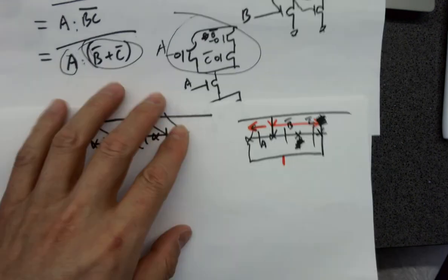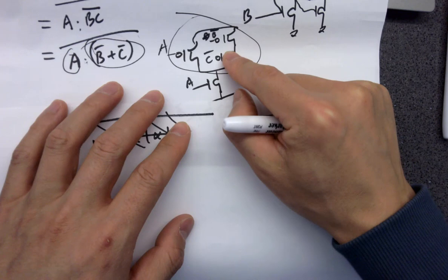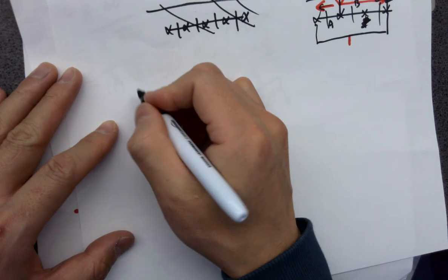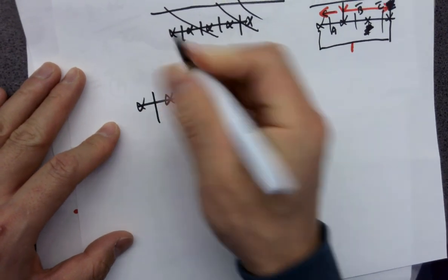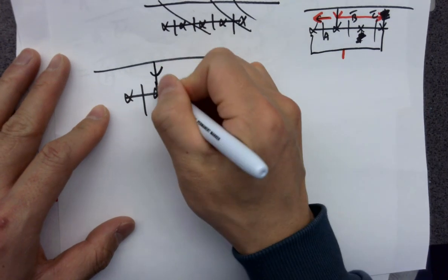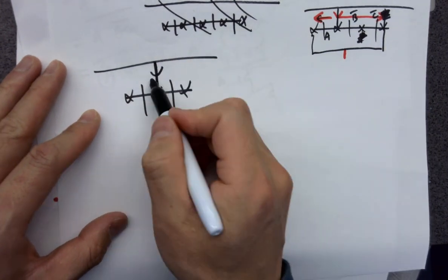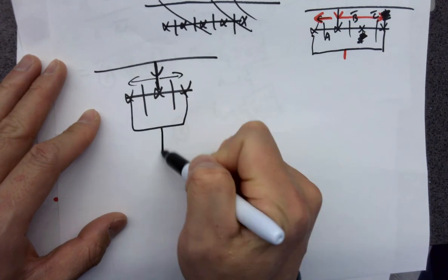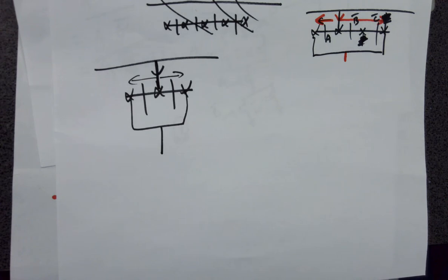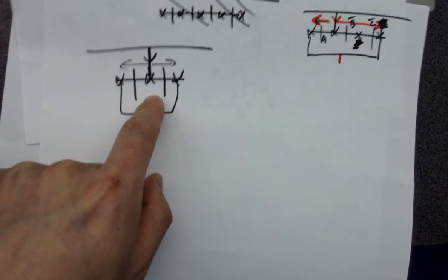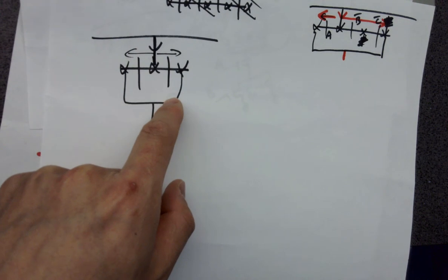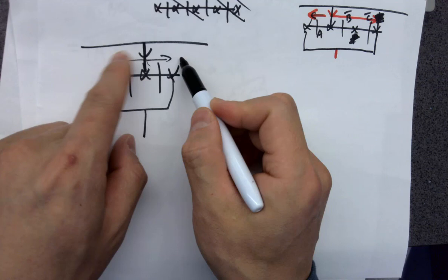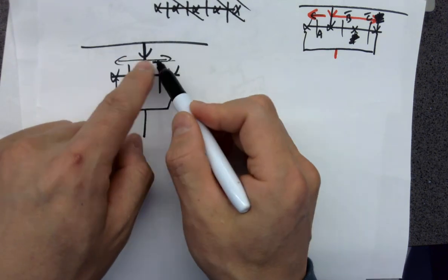See, you can actually treat these two in series as one transistor. Remember when we do the NAND gate, right? When we do the NAND gate, 1, 2, 3, so 2 PMOSes. How do we do it? One current flowing down, so it's a metal 1 wire here, and then it's getting split into 2 branches and merged over here as metal 1, right? So that's definitely 2 transistors in parallel, no problem. No problem on this, right? Any question on this one? 2 PMOSes in parallel. This makes sense, right? Current splits into 2 equivalent branches, goes through these 2 gates and merges.